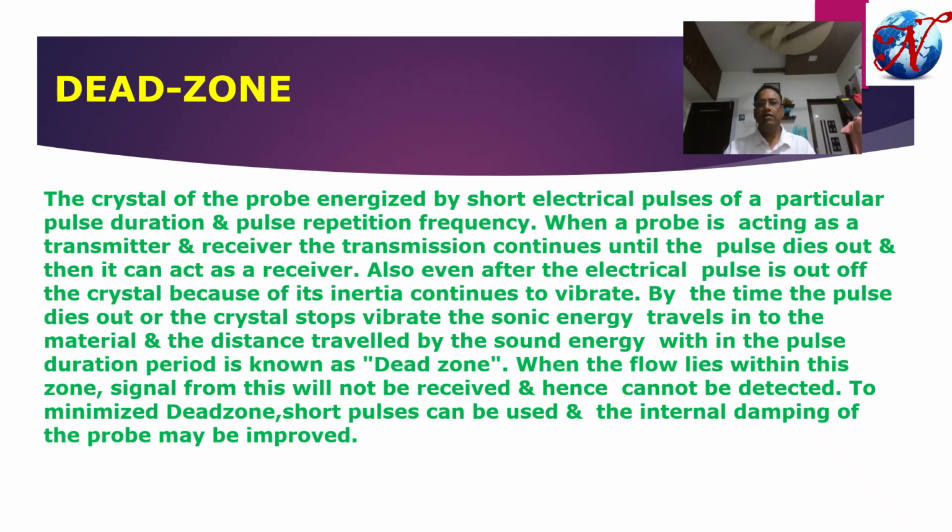Each and every probe has dead zones, and that dead zone is due to the moment of inertia of the internal crystal present in the probe. When the electrical pulse is impinged on the piezoelectric crystal, it will vibrate for a certain time period. And during this vibration, it produces low energetic ultrasound that can penetrate up to a certain distance from the near surface.